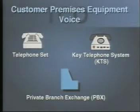Beside a plain old telephone, you might see something we call a key telephone. Now, what is a key telephone? It's a telephone set that has many lines attached to it. Actually, it could be between 2 and 5 or 6. Each line would have a respective key. When that key is depressed, the telephone would be connected to that line. Usually it includes a hold button.